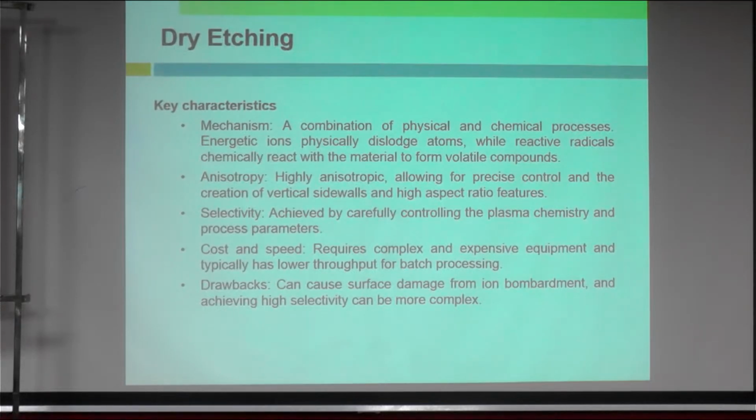In a way, it just attacks where the direction of the ion is directed. In comparison with wet etching, you just submerge the material, and the chemical will fill everywhere, and it will attack all directions without any specific direction.